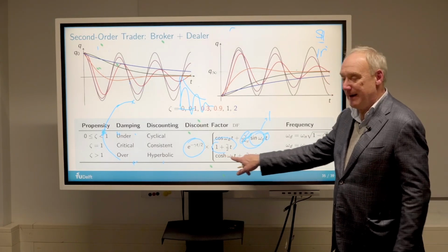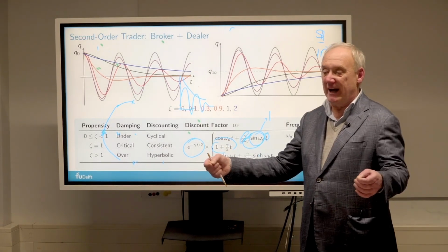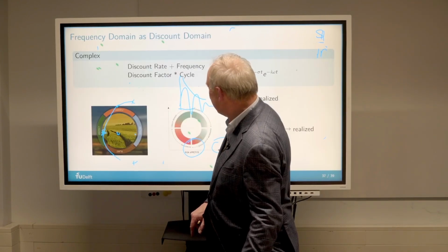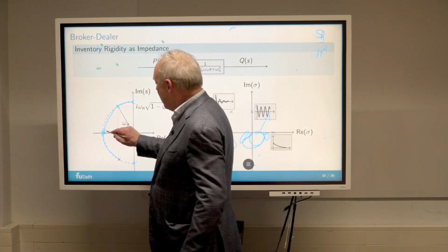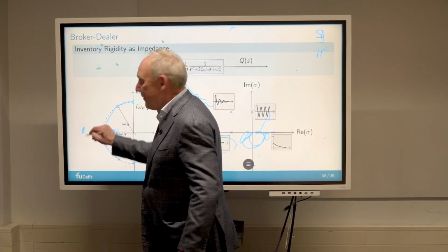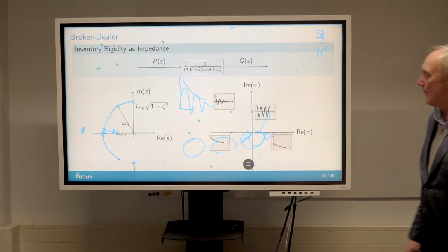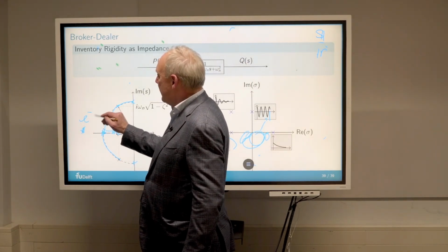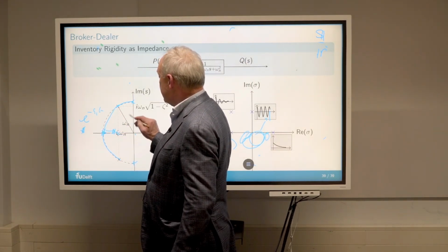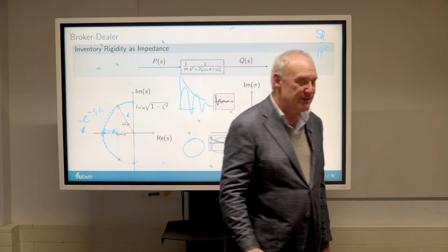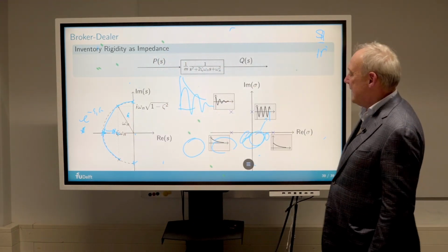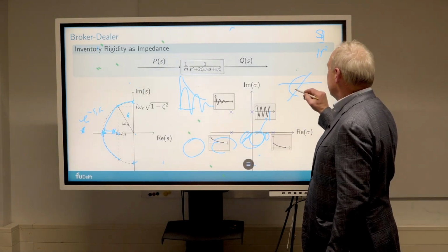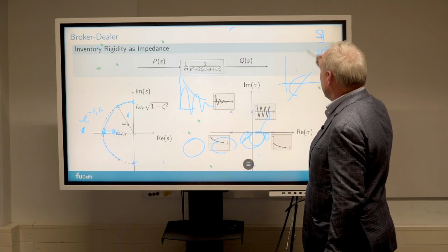So when you increase your damping further, you get these poles spreading out, with the cosine hyperbolic and sine hyperbolic. Now, how does that work? So when you go further, you'll see this pole coming in and that pole coming out. Now, you can say, why is that? Normally these get treated like some real pole, like this is e to the S1 t, and this will be e to the S2 t. But it's nicer to see it as a cosh and a sinh, because you can actually see it like this. So this will be the complex plane, and then you put a hyperbolic plane here.